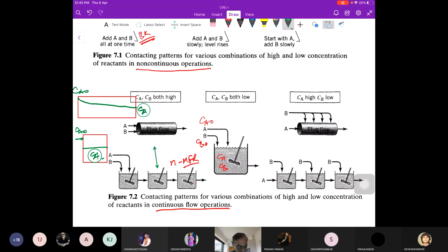समझ में आ रहा डिफरेंस दीक्षिता? Yes sir. Conversion is not important. I may have 90% conversion, but out of which 50% is undesirable, कोई फायदा नहीं मेरे को. But if my conversion is 80% and 75% of total is desirable, it is much better. So distribution of desirable to undesirable is what we are discussing here. That is important. Conversion is not important in this case.